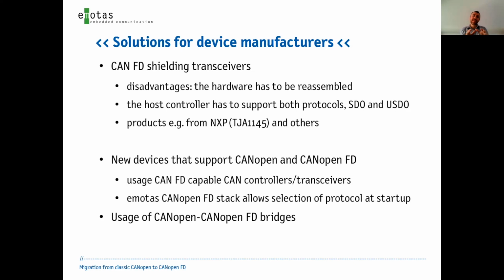Even if such devices ignore CAN FD frames and can receive and send classical frames, you still have to use the old classical CANopen protocol to address them. So your host controller has to be able to support both CANopen FD and classical CANopen.